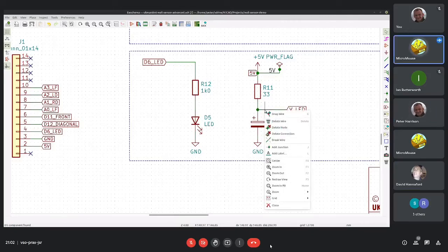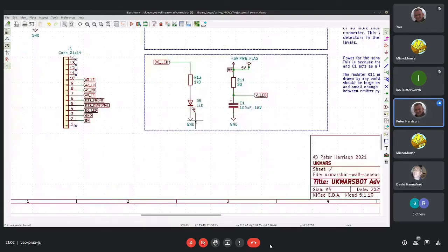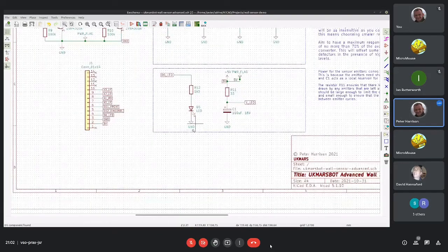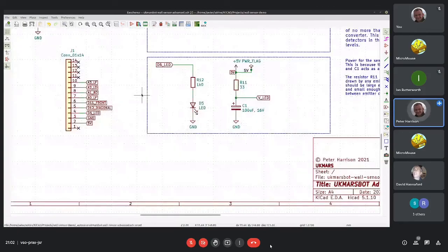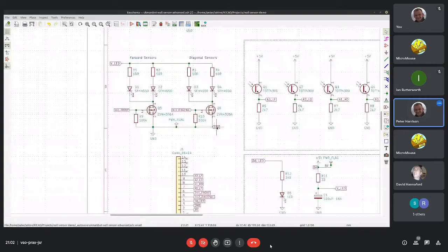Right. But obviously the question is whether that ground and that other ground will be connected together. They are. And I think the names on here do indeed imply the name of the net, right? Because they are connected together. So yes, I was not following what you were saying. They are connected together. The specific error is just about having unique labels. It's not that this is not called ground. It's that this label is lonely and needs a friend.